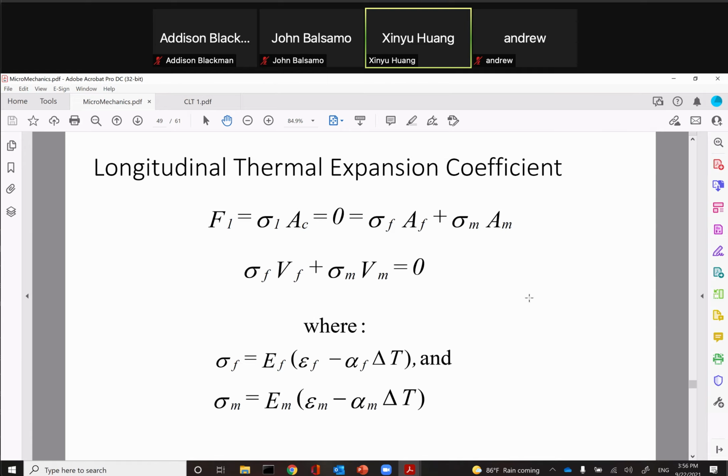If you cut the material in half, is there any stress in the cross section? What would be the stress? If you imagine you cut a material in half, what would be the stress in the cross section? None? Or there will be some? It's correct, it's none in the average sense. But in the microscopic sense, there's some, because certain phases are pulling, certain phases are in compression. On average, it's none, but at the local level, there is.